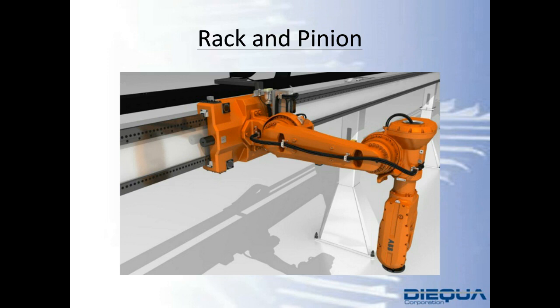Typically, the moment arm from the end of arm tooling all the way back to the base of mechanism, in this case a robot, each element needs to deliver the highest degree of stiffness possible with the greatest degree of repeatability.